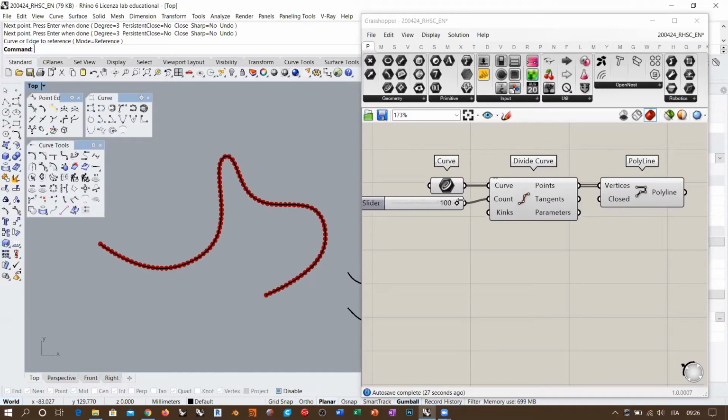Now, what the non-uniform rebuild is doing is distributing these red dots in a denser way in these areas, and having fewer red dots along these areas where we don't need them, because it is enough to have, for example, this density in this area, and eventually you need this density here in this little portion of the curve.